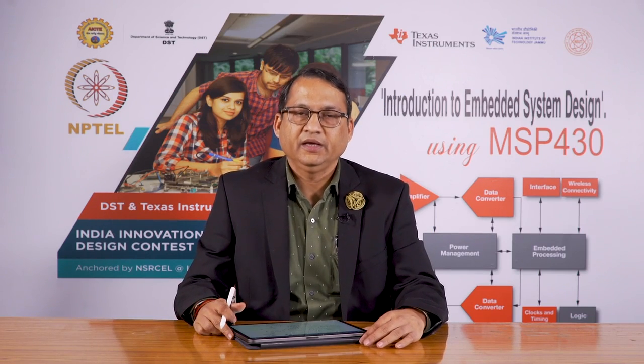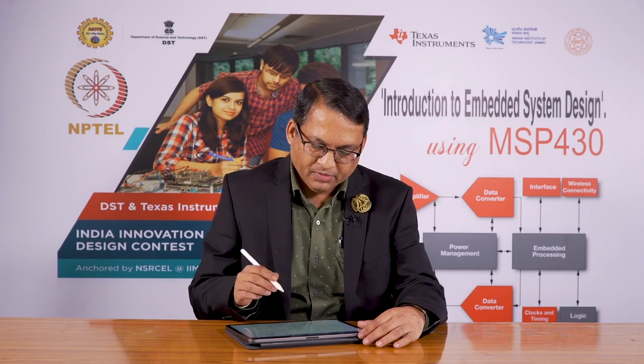Now, this is all fine when you are driving a LED where the supply voltage is constant. But imagine a situation where the supply voltage is being derived out of a battery. As you use the battery, the voltage will go down, and in this situation the reduced battery would lead to a current through the LED which will keep on reducing, because your VCC is going down. Now, how do we ensure that the LED current remains constant even though the battery voltage is going down?